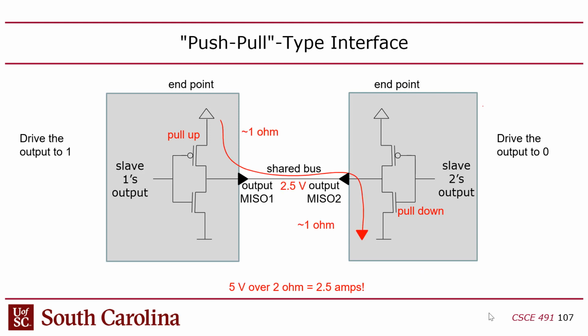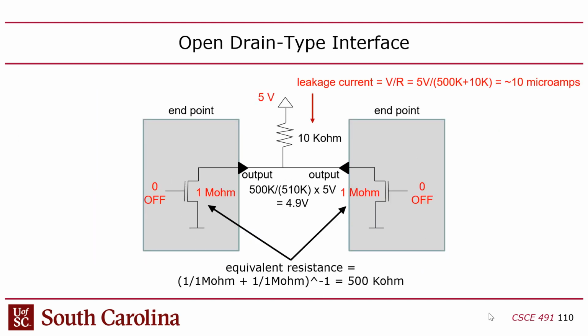On the other hand, we talked about push-pull and why conflict is bad. I2C has multi-master, but it uses an approach like Ethernet, where if you want to take mastership of the bus, you kind of just butt in and try to take control of the bus. And if there's a collision, if 2 hosts try to get mastership at the same time, there's some kind of detection mechanism for that. Ethernet has that, and I2C has that. I don't know how that works, actually. I'm kind of interested in that.